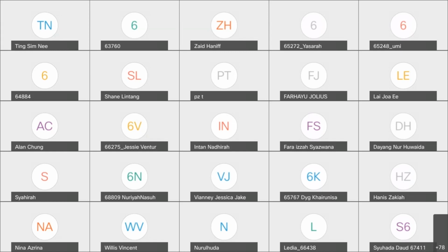Okay. After that, once you key in, the next step that we will look at is the production rate. If these 2 guys, this gang, can do this amount of work, normally they can do X amount of work in a day. And then you see that the amount of work that you have is actually Y amount. Like let's say 100 meter cube, and you've got 2 guys working. In one day they can only vibrate and everything maybe about 5 meter cube. So that is their rate, correct or not?